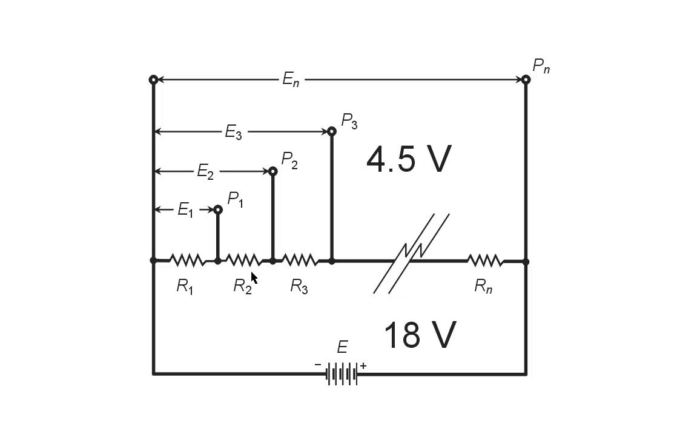That's what we want. Now R sub 2, R sub 3 and R sub 4 are also 9.0 ohms each. So each one of these resistors is going to have a voltage of 4.5 volts across it. So we have these two voltages in series. That's going to give us 9.0 volts for E sub 2. That checks out. 4.5 plus 4.5 plus 4.5 is 13.5 volts at E sub 3. That checks out. So it all checks out, and choice D, therefore, is the correct answer to this question.